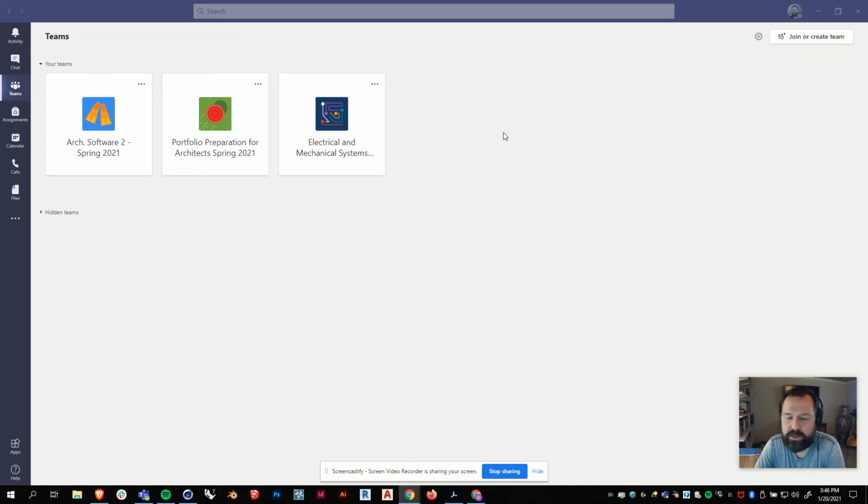I think what I just want you to make sure you understand is this idea of a centralized model that multiple people can work on at once, which we will do in this class, and that it updates constantly. And we don't need to constantly be sending files around and making sure I have the most up-to-date one when I can just reload the central file and get any updates that are out there. So that's really the biggest concept that you've got to keep in your head.